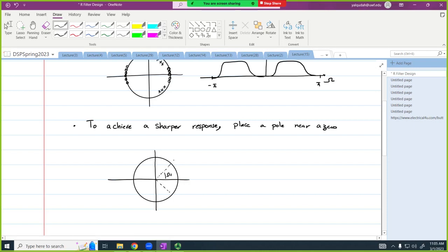Well, you said those X's up top were poles. Yeah, I'm trying to remove, not to pass. These X's made it a passband. Okay. A zero, to remove it. A zero on the unit circle means the frequency response at that location, at that frequency, is a zero. Make sense, everybody? So what do we need to do? We're going to place a zero on the unit circle. A circle means a zero, X means a pole.